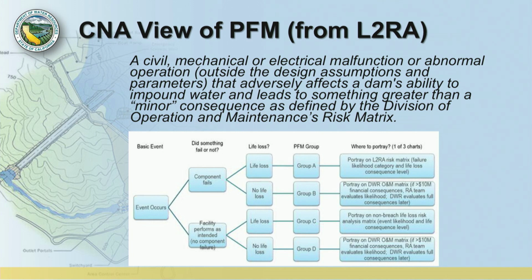And so as we move through understanding the potential failure modes, the risk associated with them, that is the probability and the consequence, we're considering not just, for example, maximum loadings like the probable maximum flood or the maximum credible earthquake, but we're considering lesser loadings too, so that we can identify what the critical loading is on this system, and we can focus our efforts on remediating or mitigating the impacts that would come as a consequence of the occurrence of that event. We're not looking just at the biggest event.